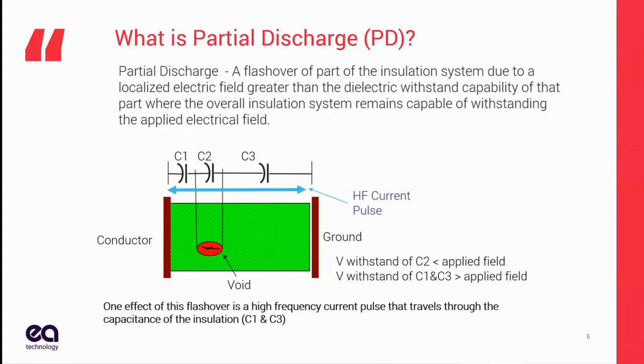So partial discharge is this current flow as a result of the insulation section not being able to withstand the voltage applied to it. So we get a current pulse that's equalizing the voltage on the capacitance. It is unipolar. It is very fast because we're talking about small capacitances. It's typically a couple of microseconds, and it's unipolar, going in one direction or the other depending on the polarity of the sine wave.